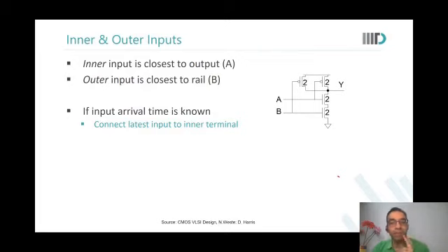In this particular example, if you know that there are two inputs A and B, and you know that the first input is arriving faster, that first input should be connected to B. But in that case, if you're considering the propagation, the capacitance between these two will discharge if it arrives fast, and will not get the worst delay. We're not characterizing now. Now we are designing a path.